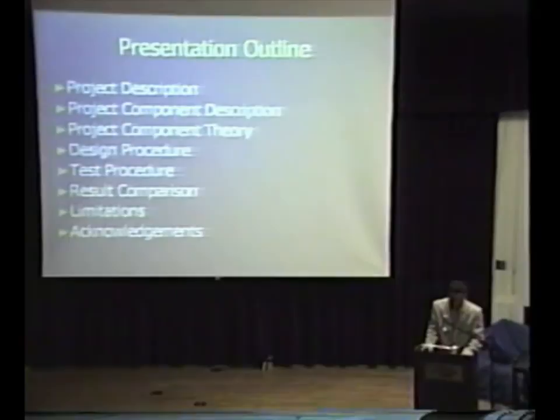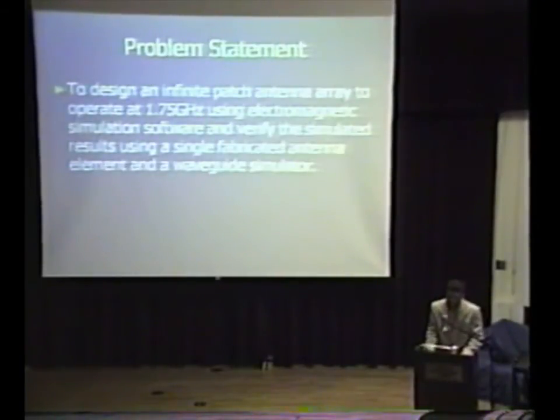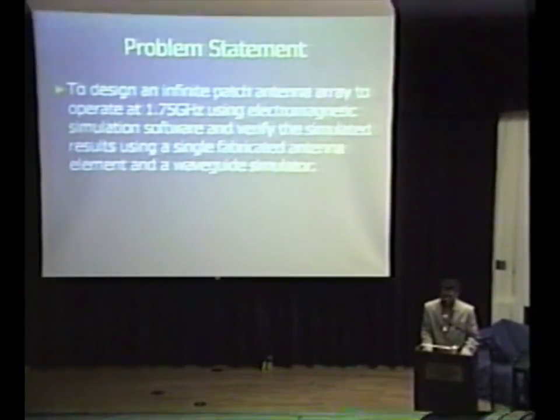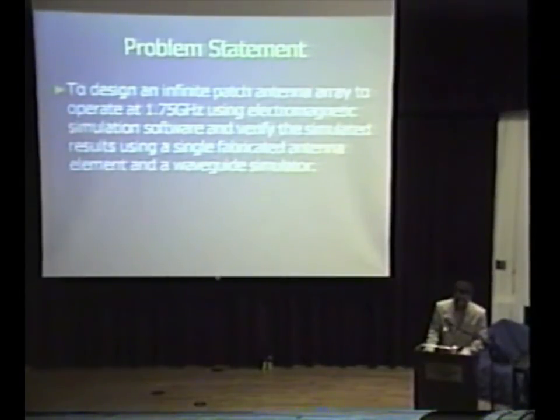My problem statement was to design an infinite patch antenna array to operate at 1.75 gigahertz using electromagnetic simulation software, and then to verify the simulated results using a single fabricated antenna element and a waveguide simulator. First off, a single antenna element is not going to operate the same as it would by itself if it were surrounded by other antenna elements. So that's the difficulty in designing an array.